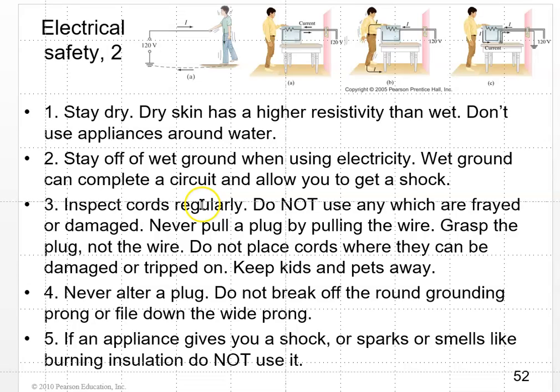Okay, electrical safety. One of the best, most important things is to stay dry. Dry skin has a much higher resistivity than wet, so be careful when you're working around water. Stay off the wet ground when using electricity. Wet ground can complete a circuit and allow you to get a shock. Inspect cords regularly. Never use any which are frayed or damaged. Never pull the plug by pulling the wire. Grasp the plug, not the wire. Don't place cords where they can be damaged or tripped on. Keep kids and pets away.